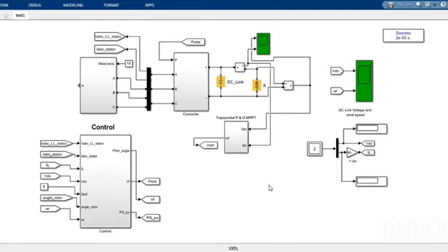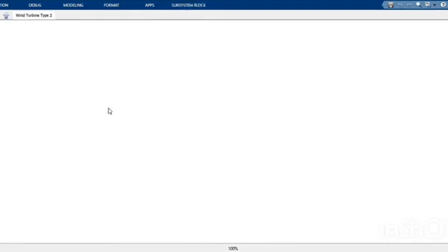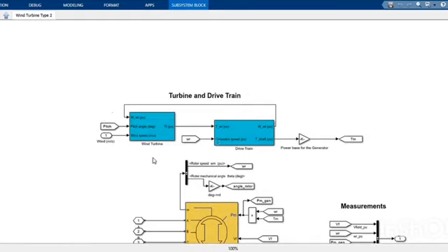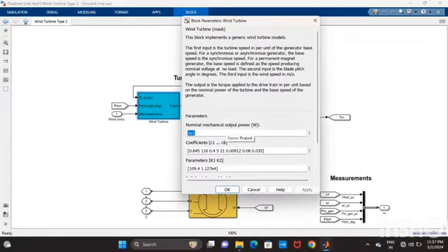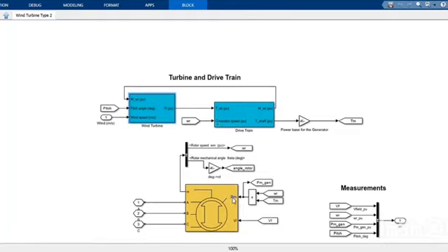This simulation presents the MATLAB model of a 3 kW wind energy conversion system. In the wind turbine block, a permanent magnet synchronous generator and salient pole rotor are used. We consider pitch angle is 0, initial wind speed is 10 meters per second, mechanical input power is 3 kW and sample time is 2e-6.